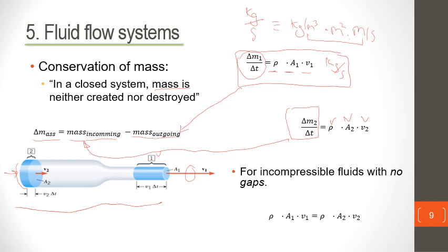So for an incompressible fluid with no gaps in between, because no new mass is being created here, the mass coming in will be equal to the mass going out. This is the conservation of mass equation.